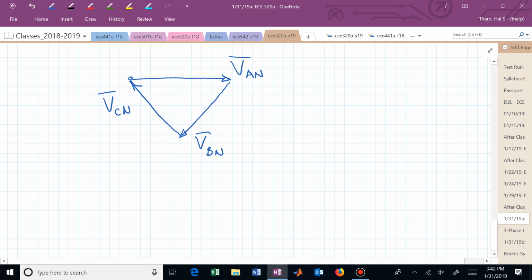So that's kind of like saying, I'm going to pick this as my reference phasor, and you just assign that phasor 0 degrees. Then everything is relative to that determination of where you said, here's t equals 0. Here's my 0 degrees phase. So no, plugging something into the wall, you're just going to see an oscillating waveform. And you would have to then say, okay, where do I want to define 0?